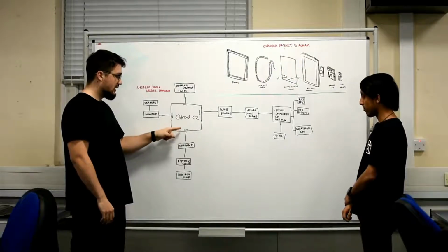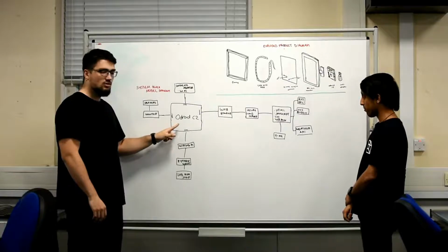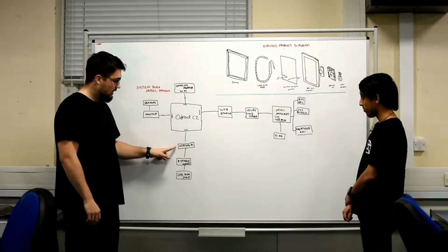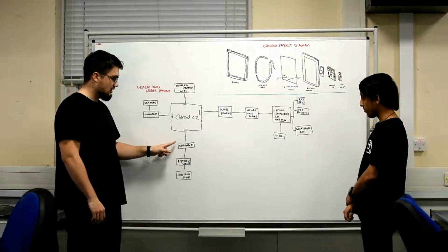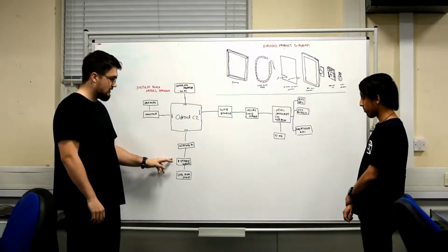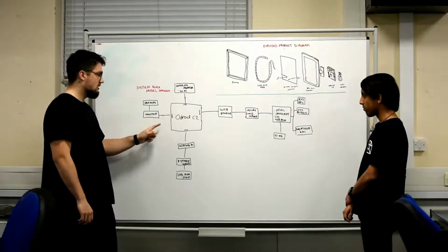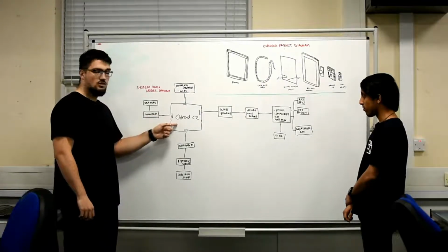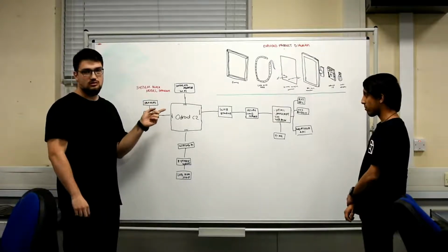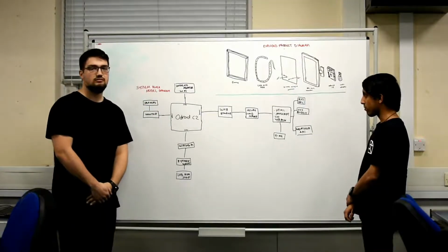For the GPIO, WiringPi is a library file that connects to the Odroid's GPIO pins. Then the Python script is using its library files, and the LED strip is being controlled by the Python script. On this side, we can see that the monitor is connected to the Odroid by HDMI, and the monitor also has speakers, so if we're producing sound, that's where we would hear it.